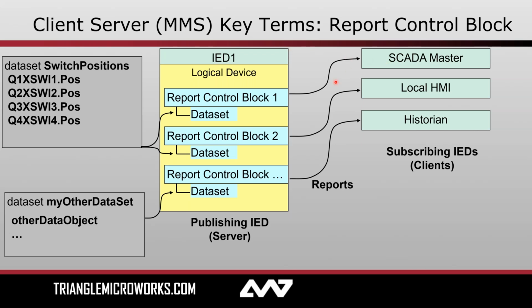So he will enable this report control block, and after that, anytime the data in this associated data set changes, a report will be sent from this IED up to my SCADA master containing what data changed. And Matt will demonstrate this for us in a couple moments using several different tools.